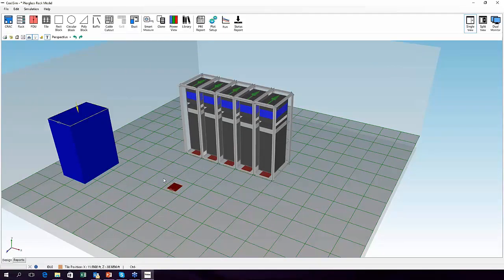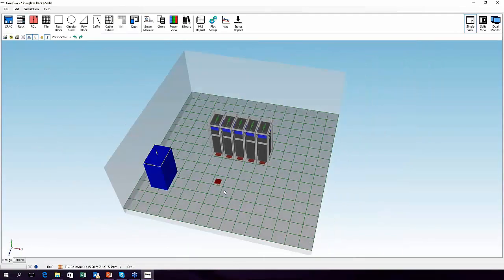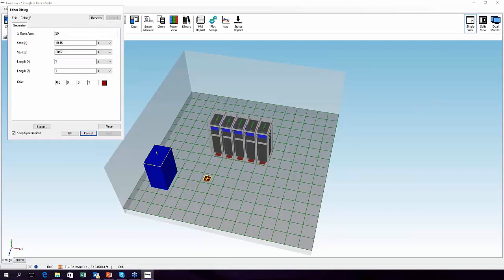If you want to model holes in the floor under your cabinets accurately, one way to do it, the most common way to do it these days, is to put this in. And then let's say that your cable cutout is not a foot by a foot, but let's say it's 3 inches, so it's 0.25 by 0.25. That's not unusual to have it 3 inches. You can also switch to inches. That's pretty small. That's going to cause the mesher to go a little crazy, but that's okay.